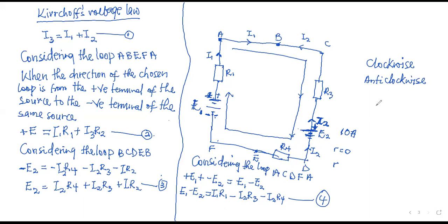In Kirchhoff's law, sometimes your correct answers can be positive or negative. If you solve a loop question and your answer current value is negative, it only means that the actual direction of current flow which you took is against what it must be.